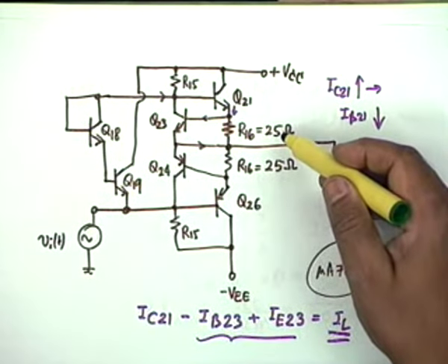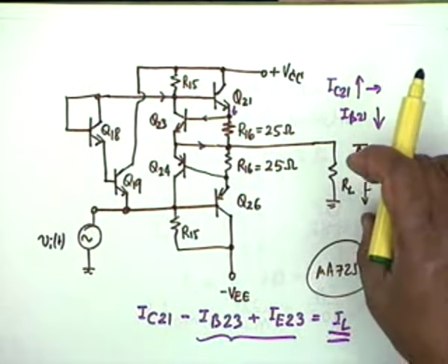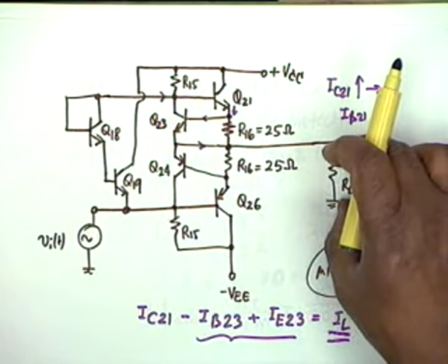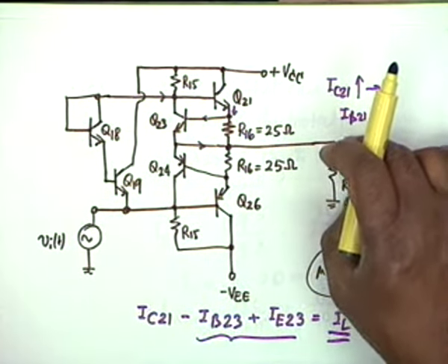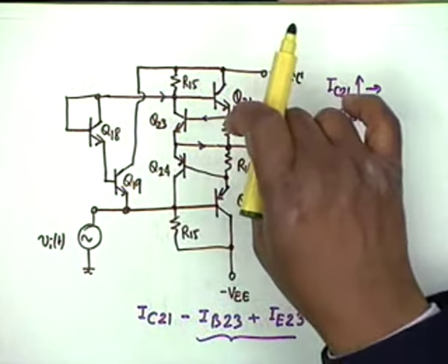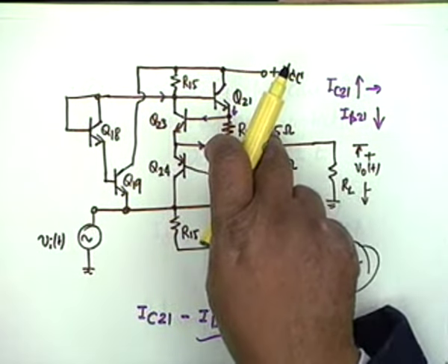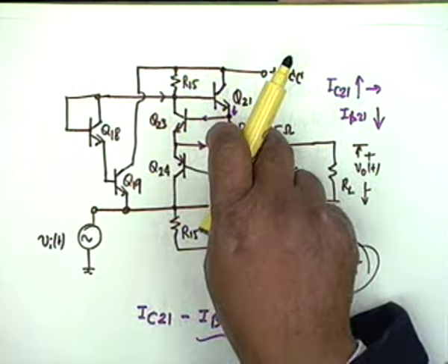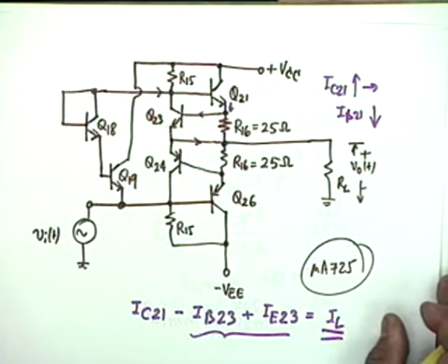R16 is 25 ohms. So, this swing cannot go to 15 volt. It must be 15 minus I_L max multiplied by 25. Is that clear? So this would be slightly less, but the end justifies the means. We found out this load, minimum load, to be 750 ohms.